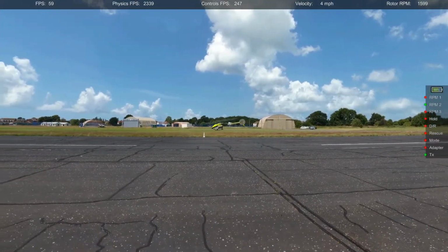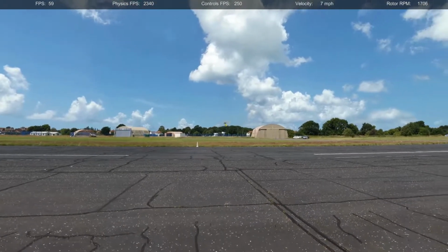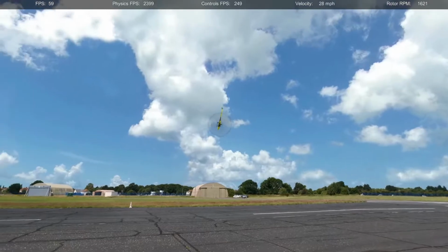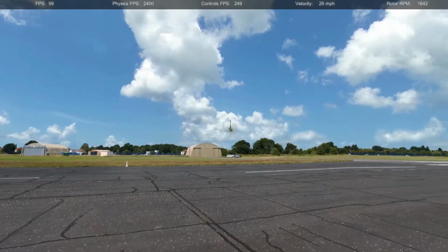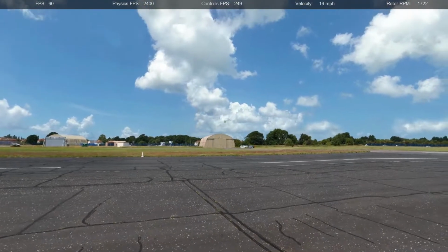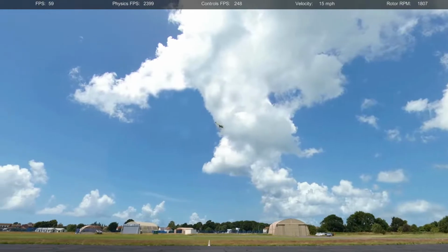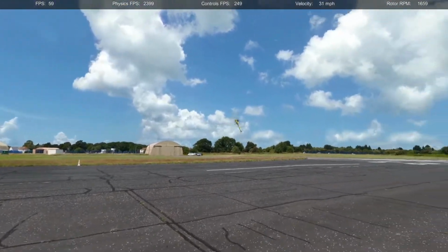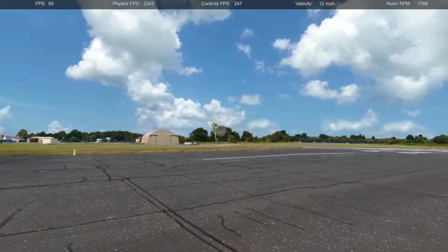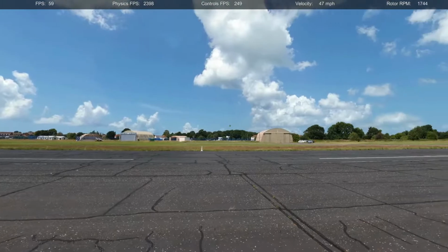And you can see that down here in the lower right. You notice that on the left side of that it says minus little d, capital D. Well, that means there's a negative change in drag on the winglet. The winglet actually produces thrust. So if you cut the winglet and you put a load cell right there and you flew the airplane, you'd find out that the winglet's actually pushing forward on the wingtip. And this is the way that winglets reduce drag on aircraft.